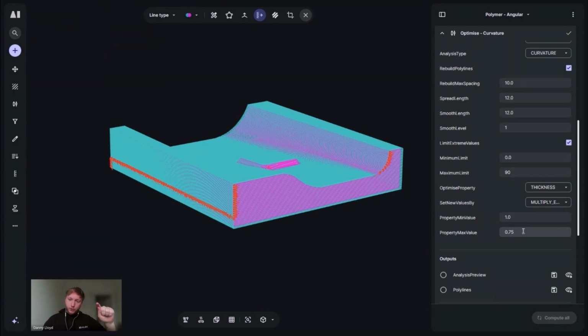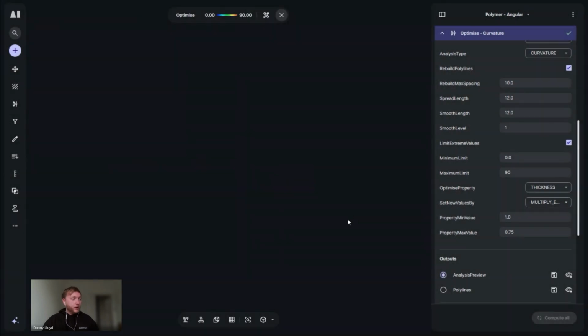As you approach sharp corners, your robot is going to be cruising at a normal speed, and then it will slow down, and then it will come back out. And the RPM of your extruder will be at a consistent rate, assuming that it's at a steady speed. That often means you're over extruding at the corners. This is seen a lot of the time. So what we're doing here is applying a difference in extrusion rates in the corners so that it will even out and give you the exact extrusion that you need.